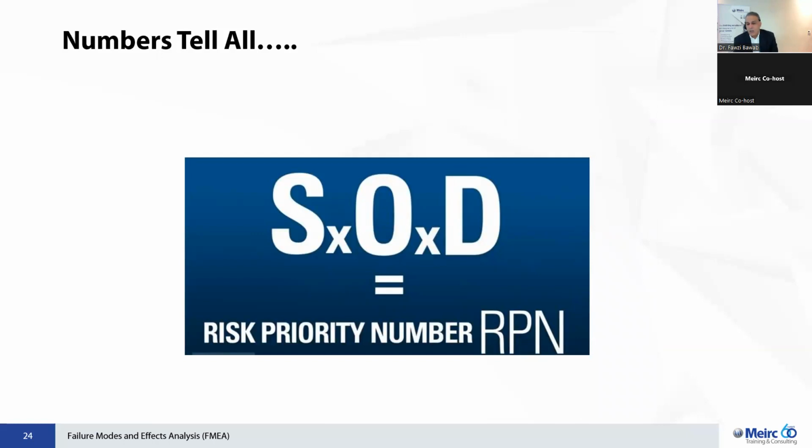And this is where the RPN, which is the way that we do the FMEA calculation of risk, comes in, and we assess the three elements, which are severity, occurrence (probability), and then detection. Of course, the S and the O, the higher that scenario, the higher the number. And we take an approach where we use 1 to 10. And then, of course, the D is asking, is there a way to detect the failure before it happens, or does it give you a sensor or an alarm? Then, as the detection goes higher, the number 1 to 10 would go lower. And hence, a higher RPN tends to be more of a concern, so the priority is defined by having a higher number.